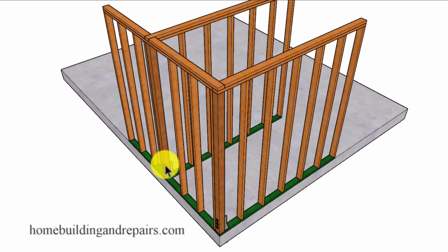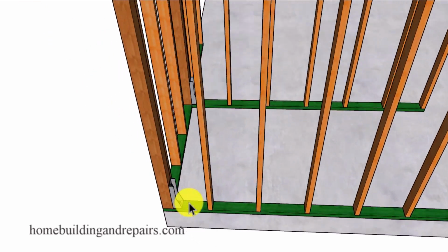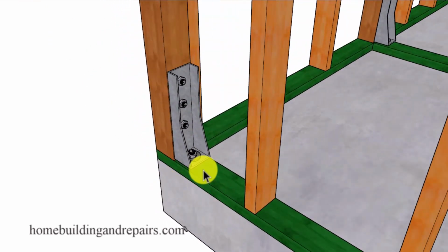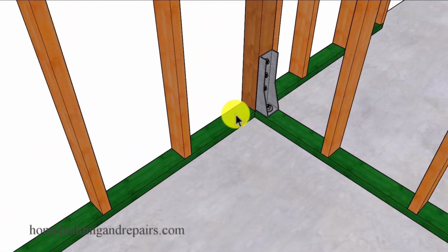And even though this one here won't always be called out by the structural engineer to be located right here, the corner one probably will. This is the ideal location for the corner and is probably going to be specified with a detail, or the engineer will provide you with a specific location on the floor plan.